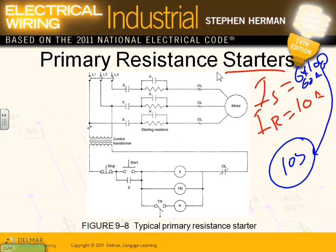The smarter folks came up with a couple of old methods. In this system, when you push the button to start, you energize this coil and close this contact. Now the current goes over here through the resistor into the motor, and I'm going to track just one current. If the voltage here is 480, I'm going to lose 200 volts across this resistor, so that will give me a voltage of what?